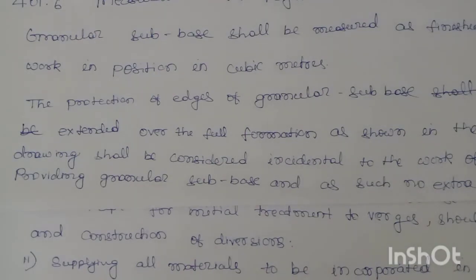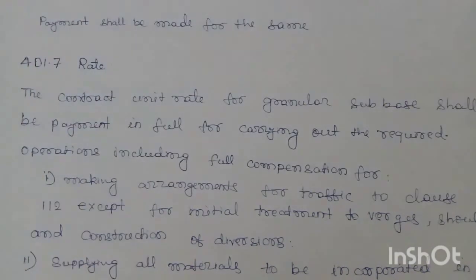The protection of edge of granular sub-base extended over the full formation as shown in the drawing shall be considered incidental to the work of providing granular sub-base, and as such no extra payment shall be made for the same.